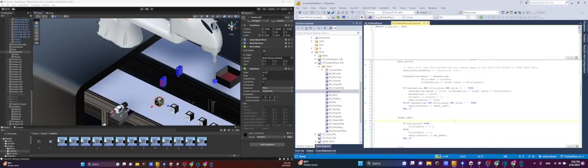Now, the next thing I want to do is create a message here. If I'm going this route here and going to this index conveyor 1 state, I also want to issue a message. My FB pick and place is extending an event system function block that I created. My method create message.